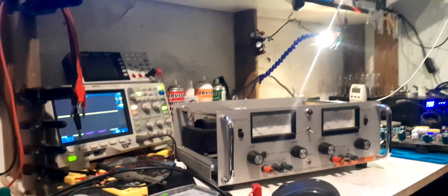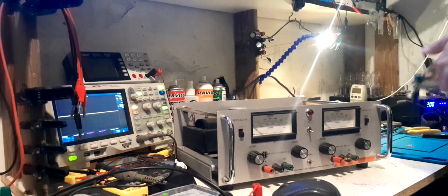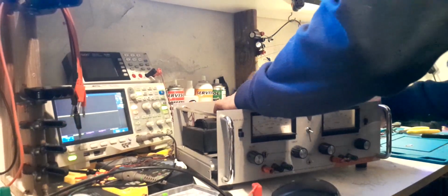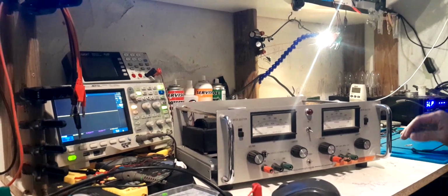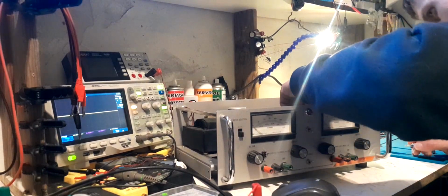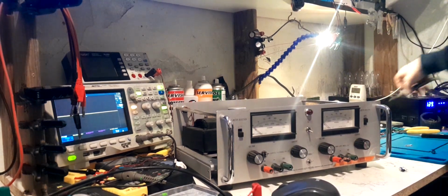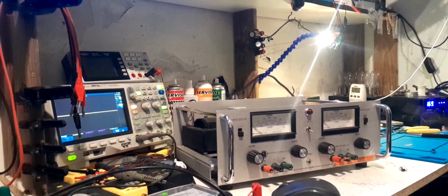Because I'm going to have to put that reference in with the 47 mic cap on it and put a load on it at startup and see if the current overshoots for a bit. I'm already suspicious that 47 mic is too much. If you all get where I'm going with this. If not, just bear with me. I'll pause the video whilst I make the connections.